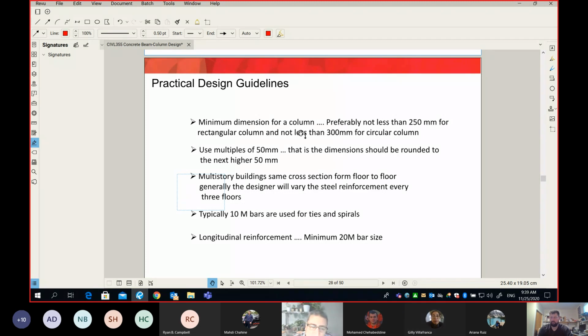No, no. We don't do that. So there is a rule for the designer, again, it's not a Bible, you can do whatever you like, but practically you should change your column dimension every 3 to 4 floors. Okay, it's easier for construction, easier for forms. Every 3 to 4 floors. Even if it's not required by the size, you need to keep your column dimension the same for 4 floors, and then it changes and so on and so forth.